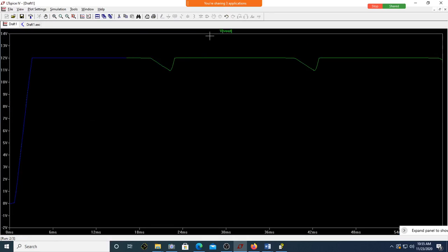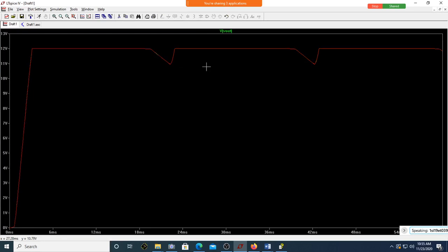Can you see this happening? Yes, sir. This is 30 ohm resistance. Now we can see it's not a constant voltage. So there is a problem in your output voltage because you are trying to draw more current. Yes, sir. So this is called load regulation.